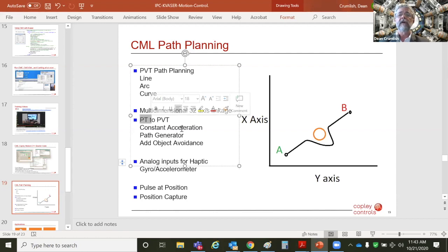And it's kind of like robotic control. Now, when you get into 40 axes of motion control, not all of them have to be PVT. Some are just simple point-to-point moves. So CAN lends itself really well to applications that have a few highly coordinated axes and a whole plethora of simple point-to-point moves with, like, I don't know, 300 IO points. Okay, so all that's fine on a CANopen network.